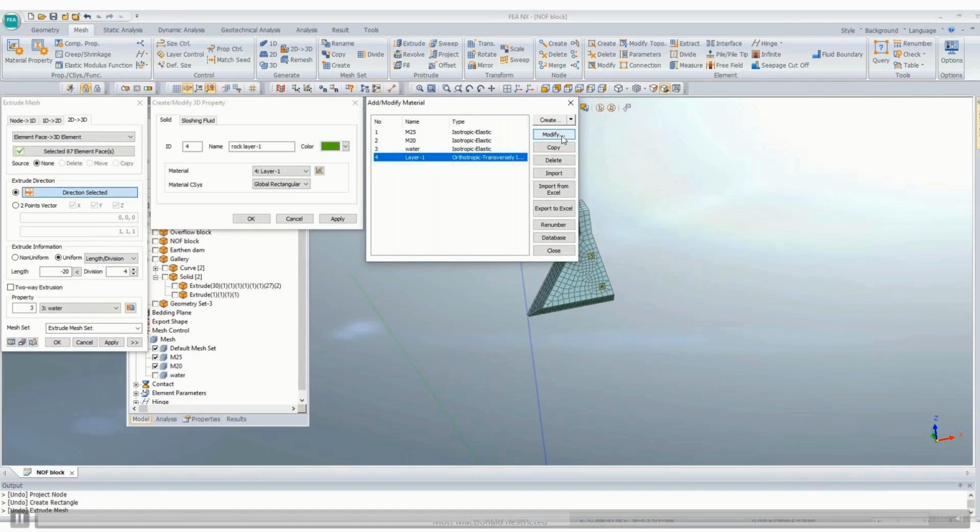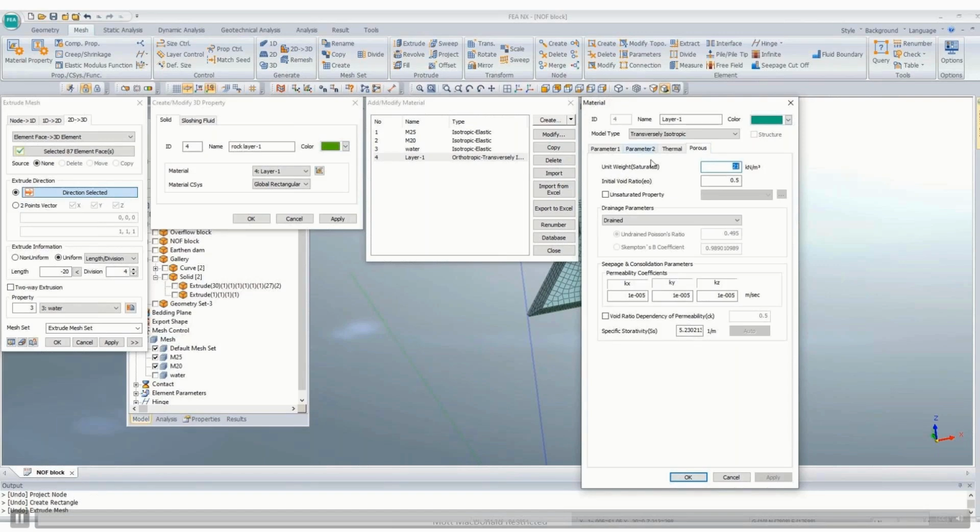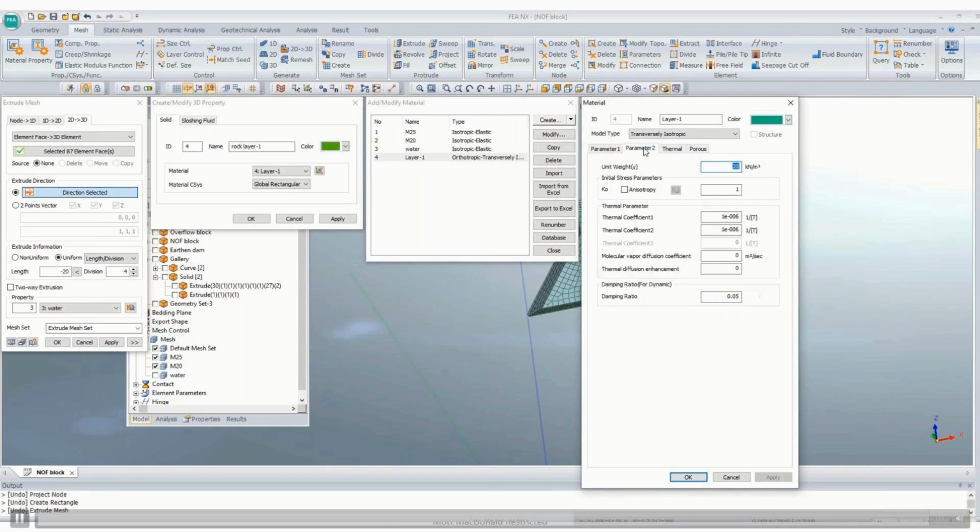I can have massless, dampless foundation. I can use these porous parameters, void ratio, unit saturated weight, permeability coefficients. I can have a water table, so I can insert various geotechnical properties. Those are more applicable for soil, where we have to carry out liquefaction studies. For sound rock in a confined environment, during an earthquake, it will vibrate almost in phase. We are more interested in the structure constructed above it. That foundation has undergone various earthquakes and other forces, and it is stabilized now. If it is RBM or loose material, then these are of more interest.